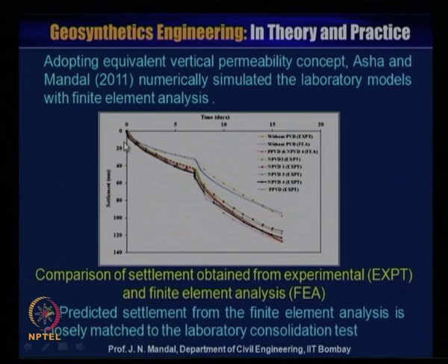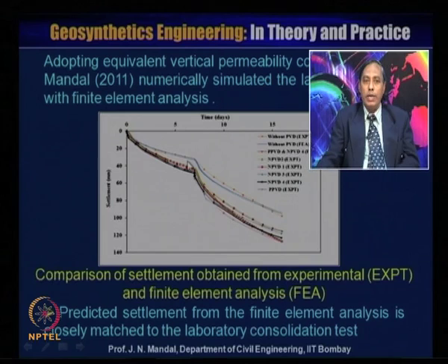You can see how the settlement increases with time, then after a certain time it increases again like this for all these PVDs. You can match what you obtained from the experiment and the finite element method. It has been observed that there is quite good matching between the experimental and finite element method, and the predicted settlement from the finite element method closely matches the laboratory consolidation test.